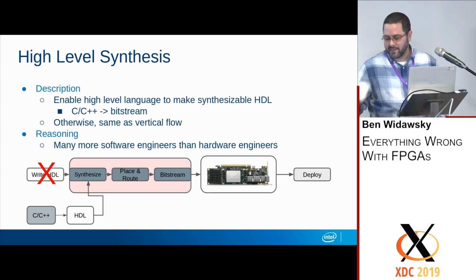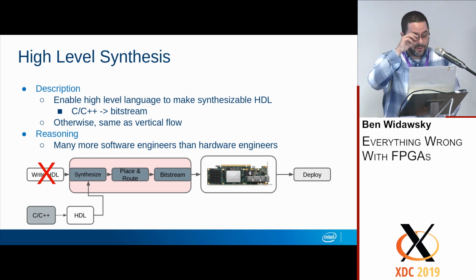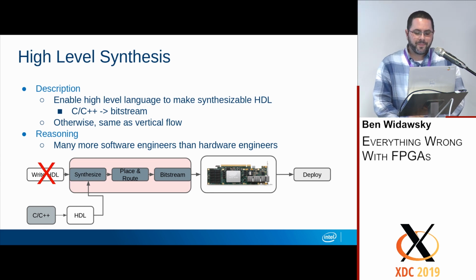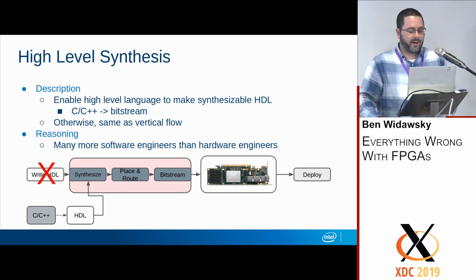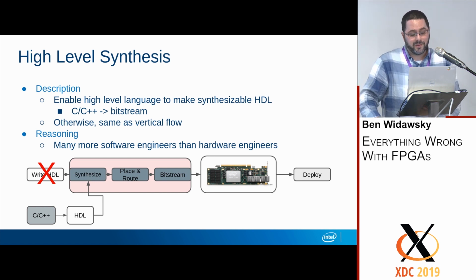There's something called high-level synthesis. Some people are interested in this. Actually, it's been an area of research for at least the last dozen years, and it's been growing quite a bit, although I wouldn't say necessarily that it's popular. This allows you, using a high-level software language that probably most people in the room are more accustomed to, to create your designs. I think all the major vendors have solutions for this. I've heard rumblings of some companies working on separate solutions for this. But generally, this is just the same thing as what we described before, except maybe you'll have C++ instead of writing Verilog.